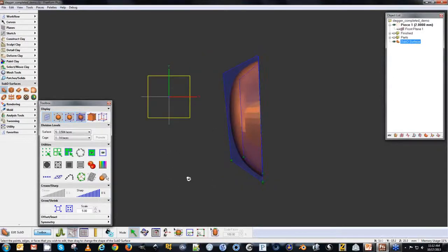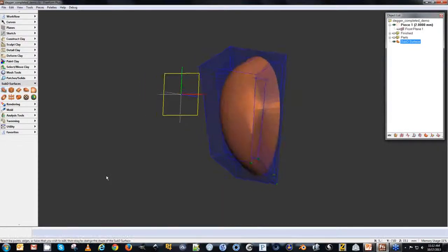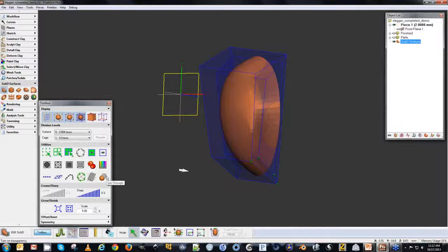So I'm going to go back to my side view. And I'm going to cut in a little more geometry so the blade has a place to sit and the handle has a place to sit. So much like I did to do the initial inside, I'm going to add a face loop here on the top. And I want to scale this face, but I only want to scale it in one direction. So I will select edges that define the direction I want to scale it in, and using the scale again, I will shrink it down, and we're only scaling along the x-axis.